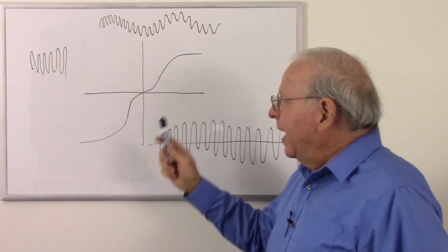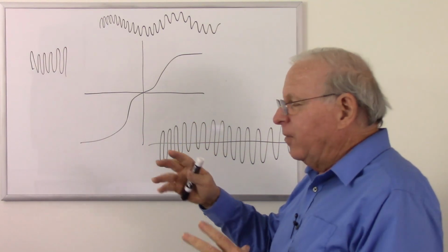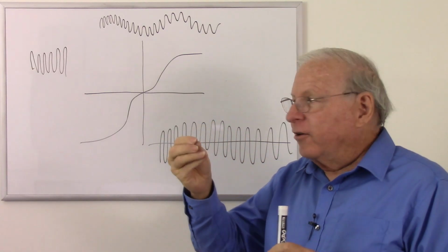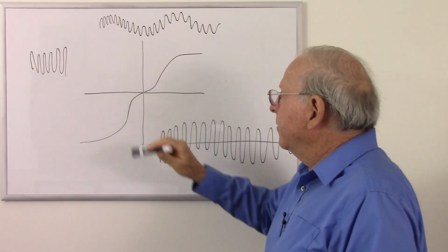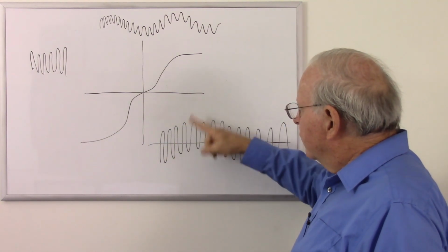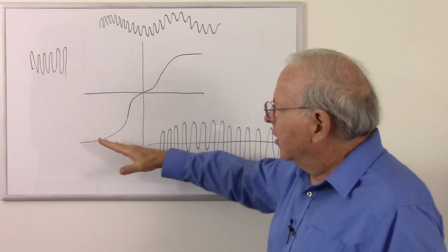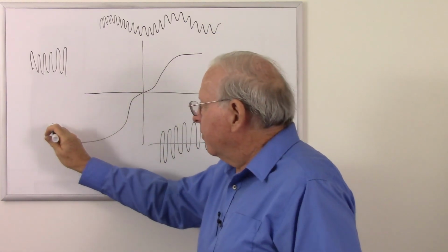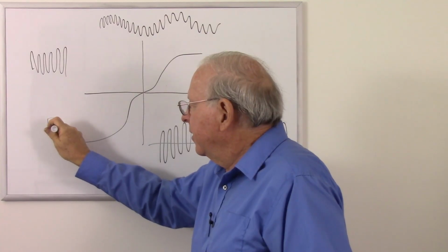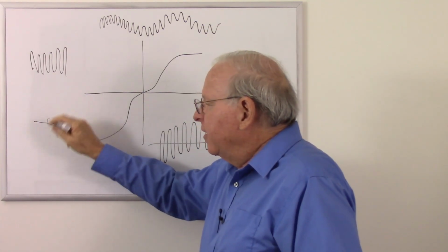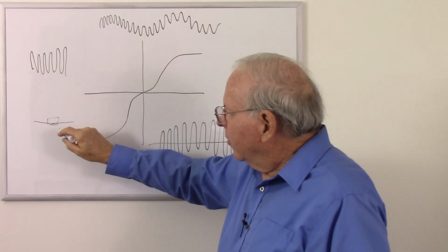So, knowing that to demagnetize something, we want to get those magnetic domains flipping back and forth tinier and tinier to get us back to this point here. Well, that's basically what's going on here. As this goes across, it's magnetizing it a lot, but as that moves away in the head, so here's our recording head here, and our wire or tape or whatever goes by there, as it moves away, we've got that alternating signal.